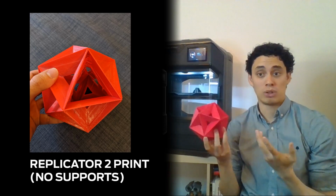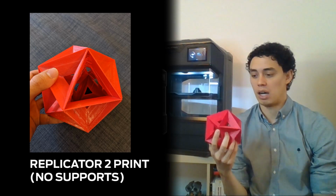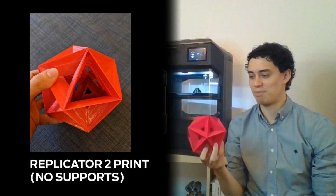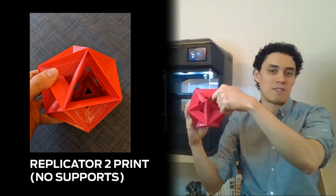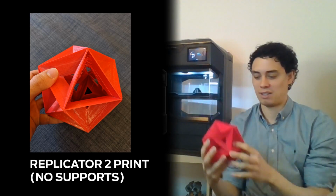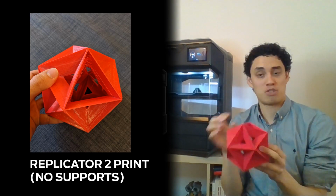The reason why I didn't want to have supports was that in this sort of hollow structure, removing those supports can be really hard. It's super tricky. And ultimately, this is actually a coin bank, right? So I didn't care much about that one face. It's an icosahedron, so I just made it so that it was mostly unsupported. It was just that little area that would have required supports, but I didn't want to deform the whole part just because of that small section.